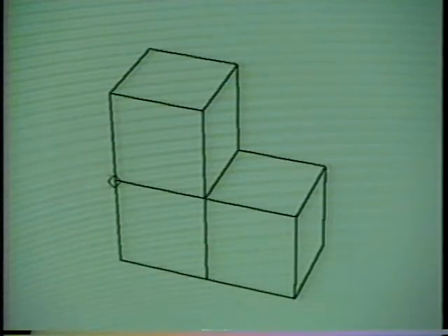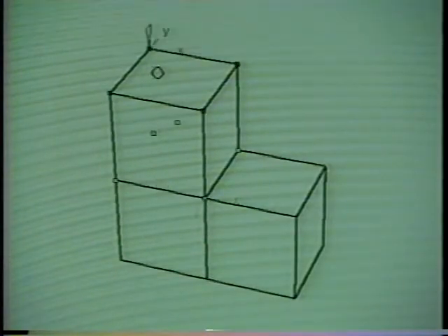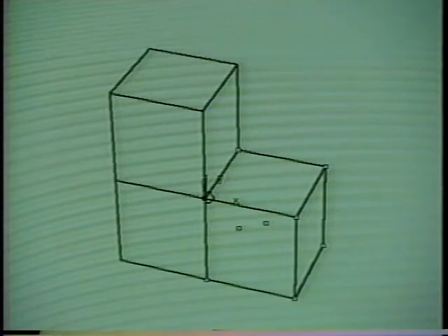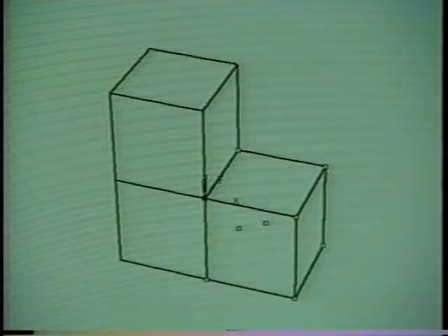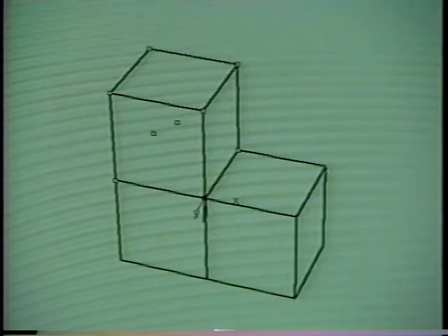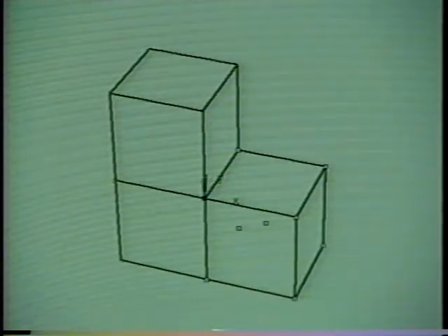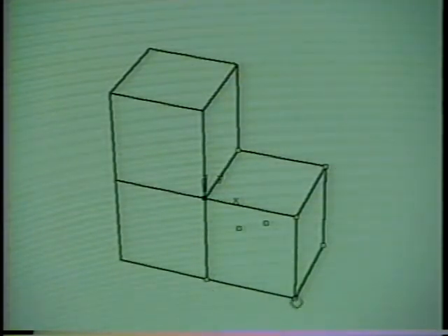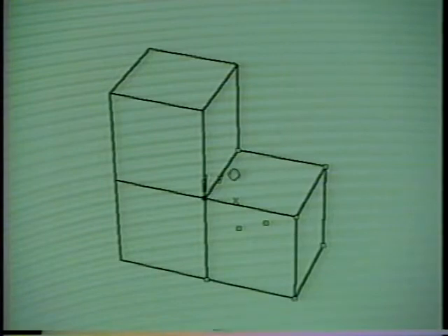Gargoyle 3D allows the user to select parts of objects by pointing at them. Pointing can be ambiguous. For example, I am now selecting a vertex, but to which of the 3 cubes does it belong? The system allows me to cycle through the vertices that were behind the cursor when the selection was made, selecting them in turn. As each vertex is selected, the unselected vertices of its cube are highlighted with white squares to disambiguate the selection.